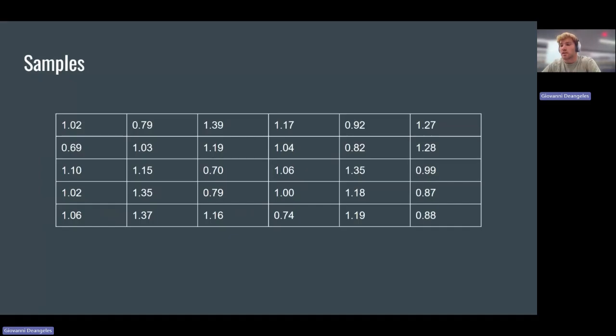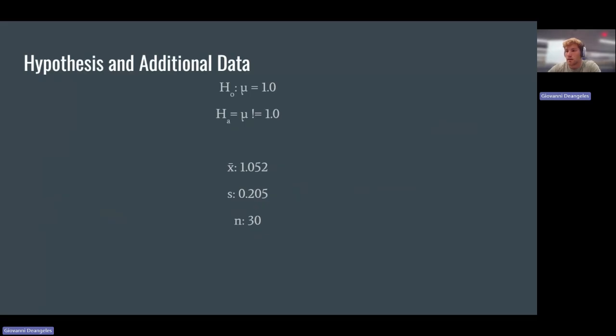Hello, my name is Gavin Quindell, and these are the steps that we are going to go through to get our sample mean, our hypothesis testing, to really understand what we are looking for. So to find the heat seal strength of the machine, we use hypothesis testing, which is a statistical method used to help identify whether a sample mean is different or within a wanted value. In our case, it is going to be 1 pound of force. This is a way for engineers to be able to make decisions based on data on situations such as the heat seal strength of a machine.